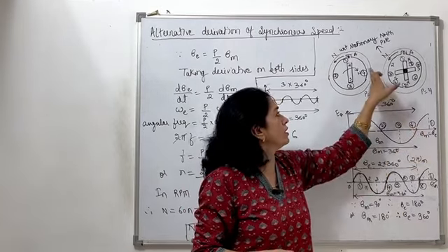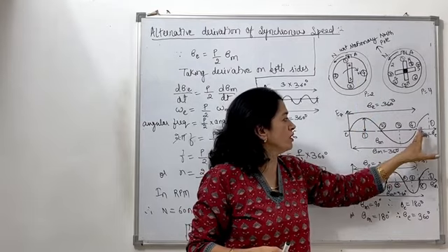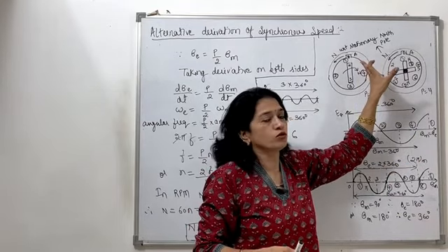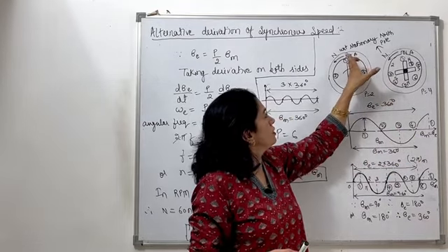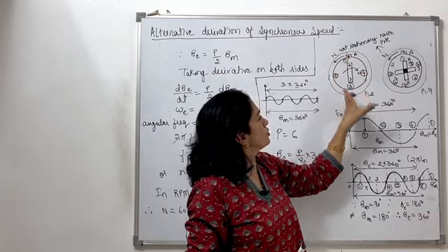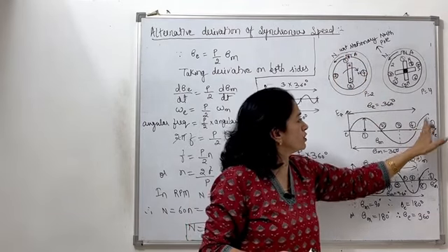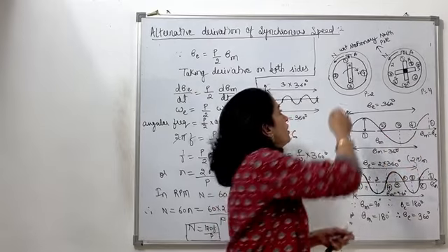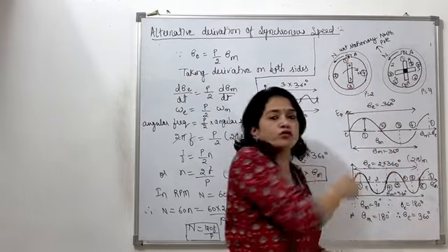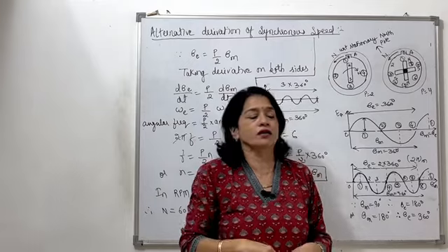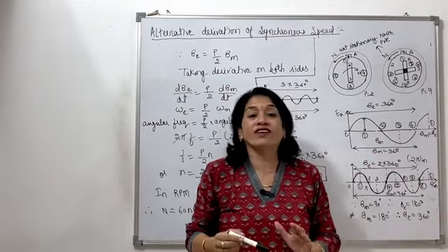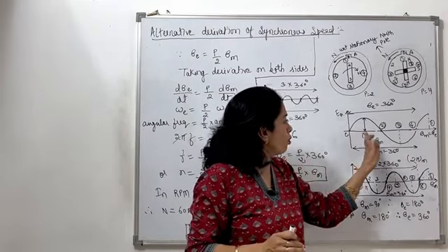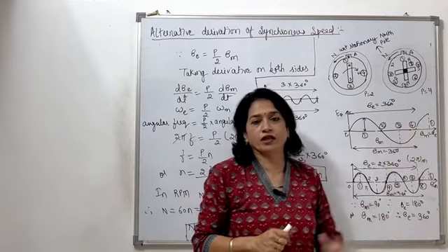So here again at the neutral position, it would be having zero EMF. And then again it is going towards the first position. So the conductor achieved one position, second position, third position, fourth position, and again first position here. So it would be having this complete cycle when the conductor itself moves by 360 degree mechanically. So it would be completing, or creating, I should say, inducing one complete cycle of EMF in that